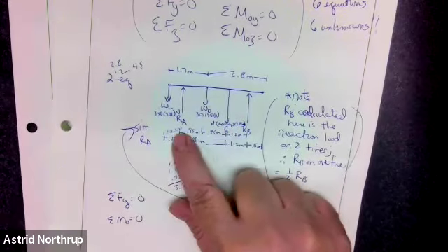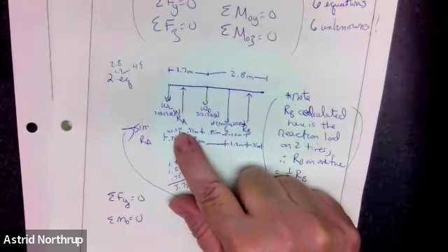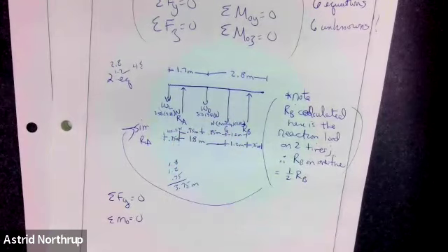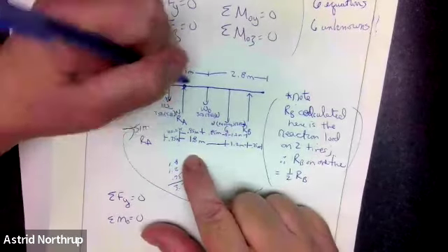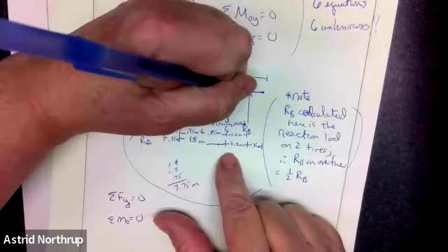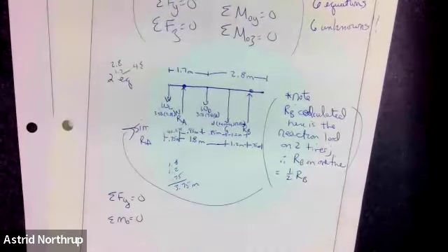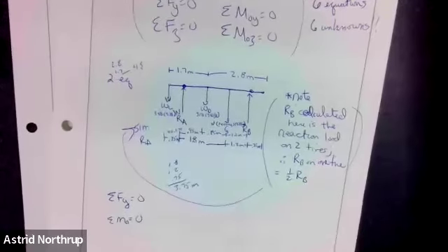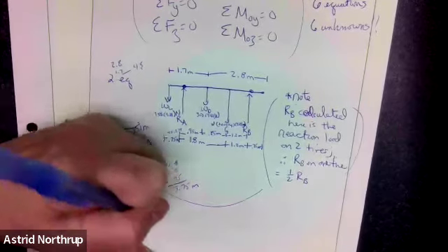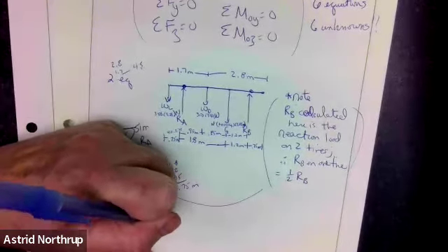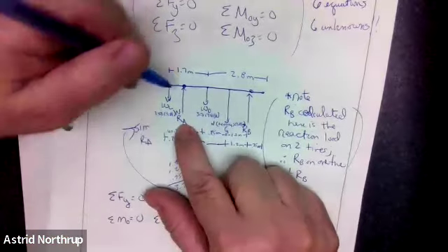So if I choose one of my unknowns as the point I'm taking the moments about, I will eliminate one of them from that equation because anything times 0 is 0. So I would probably take the moments about either point A or point B. It'll still work if you choose any other point, but if you choose one of those, one of the unknowns will go away and you can solve the moment equation directly. So let's say here, choose summation of moments about A equals 0.